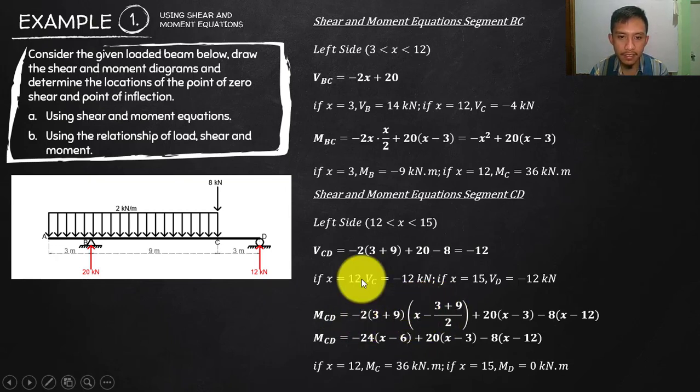And then the distance of that is located at, okay, X is up to the section I cut here, but that length of UDL is just 12. So let's say that is the middle. The middle of 12 is 6. And then X is up to that A. So somewhere here, the distance of that center to that point where I cut is X minus 6. Half of that 9. So that's why this one, 12 divided by 2, that is 6.